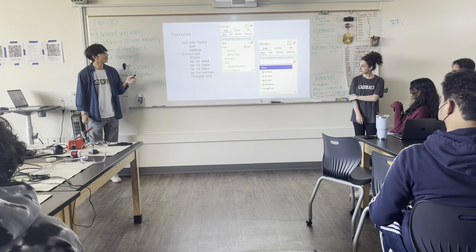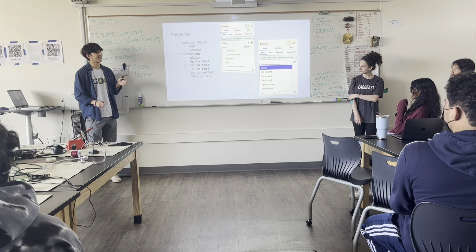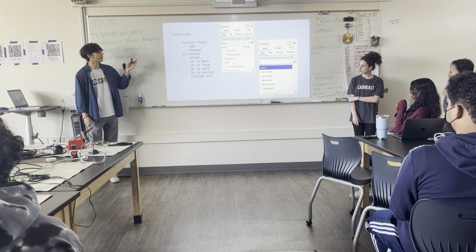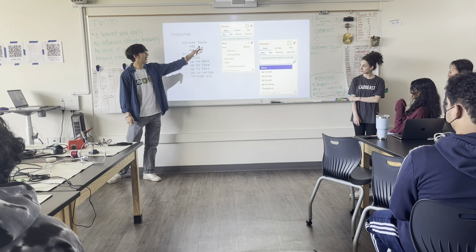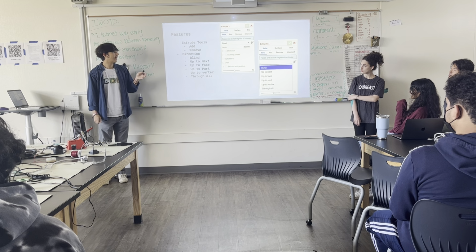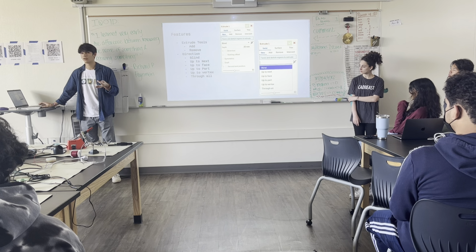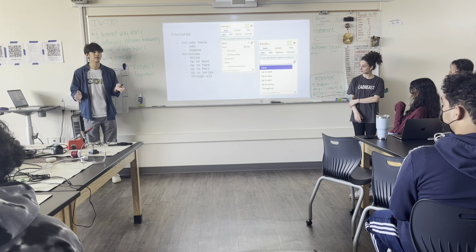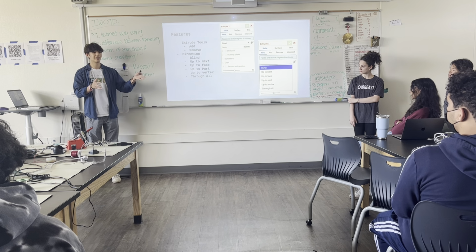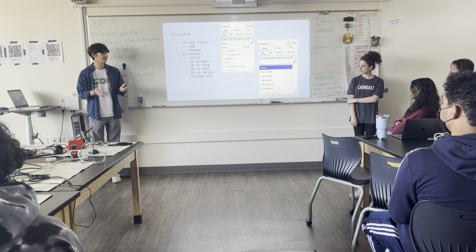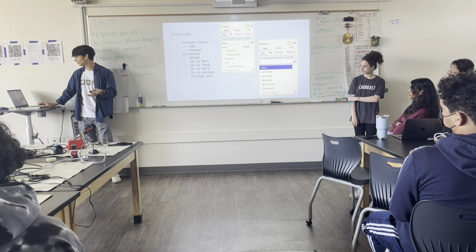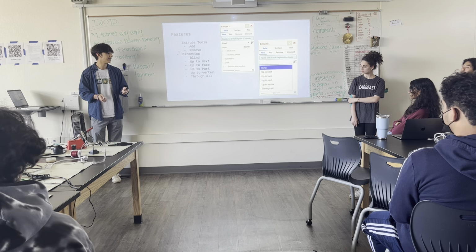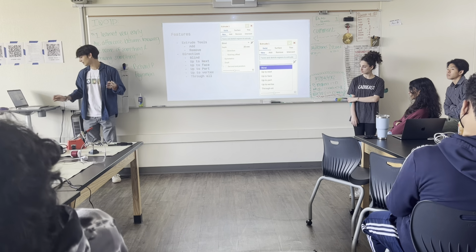Here's how it looks on Onshape. It's a little bit different than other CAD software that I've seen. Under extrude, you can choose to add or remove, and that'll be either an extrude or a cut extrude. You can also set the direction or how far you want it to extrude. Blind just means that it'll go a set distance and you choose the distance. So if I know that I want to make this thing 10 millimeters, I'll just use blind. But if I want it to go all the way through to a specific face, you have this drop down menu of things that you can choose. It just helps you decide what you best need.